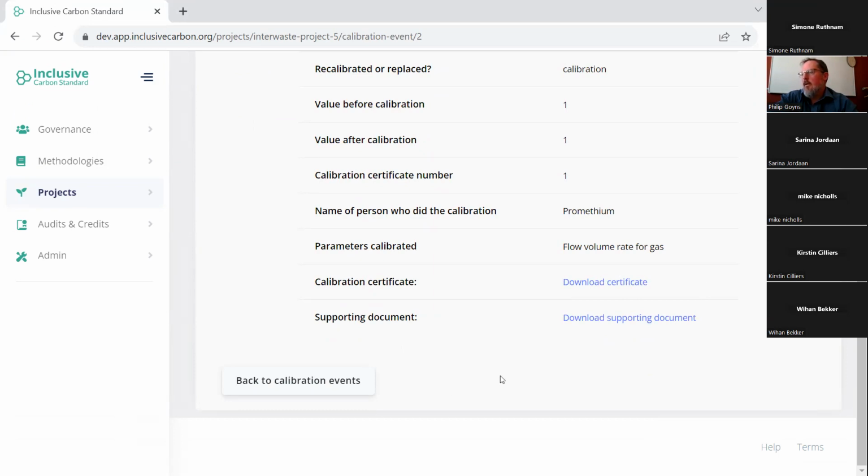calibration certificate for that. And what will happen when one is doing a verification is that the auditor would want to see the calibration certificates for the different instruments that you have. And what they would then check is, have all the calibrations been done when they should have been done at the required calibration interval. They will also then check if there's a missing calibration, has there been an appropriate adjustment to the measurements that you've taken based on the next valid calibration. And if the instrument has drifted out of calibration, then an error adjustment must be applied to the measurement for the calibration that was missed.